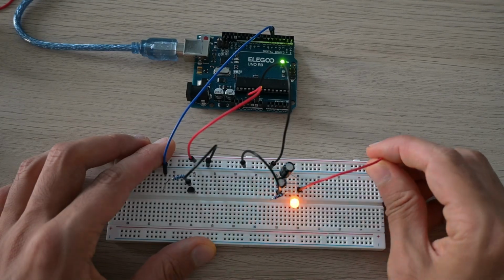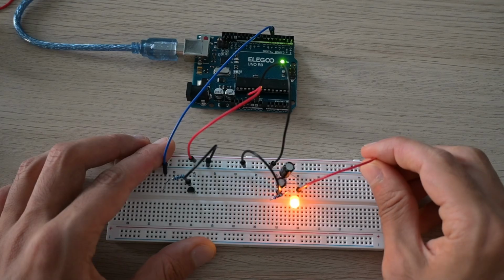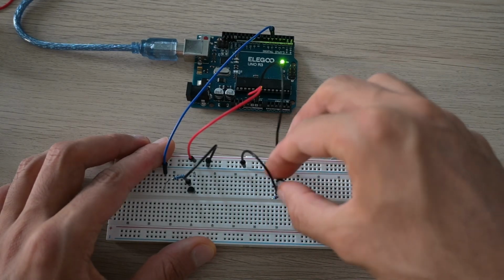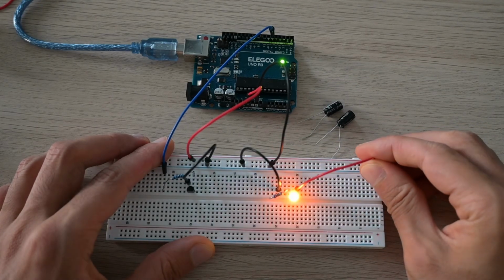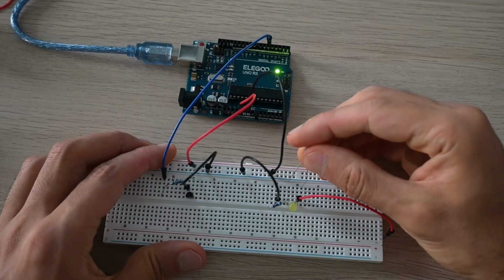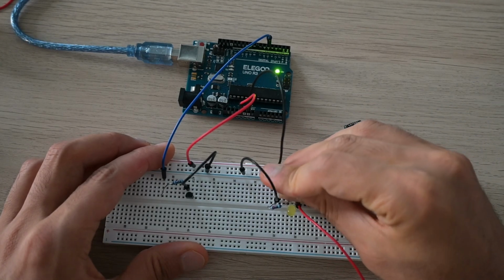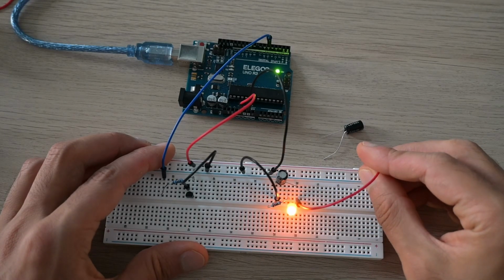This is because capacitors are essentially energy stores, like batteries, with consistent charge and discharge times. So here, I'm going to remove both of the capacitors, so you can see how immediately the LED changes its intensity. But if I put one of these back, and by the way, I had 2 before in parallel because their capacitance was summed up and the effect was more apparent, but regardless, you can see that now it's smoother.